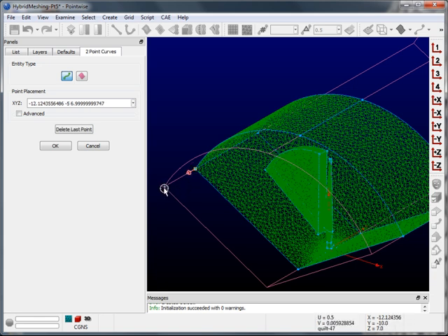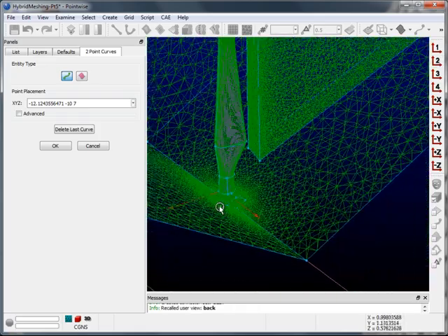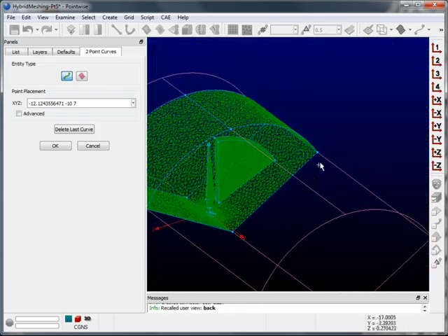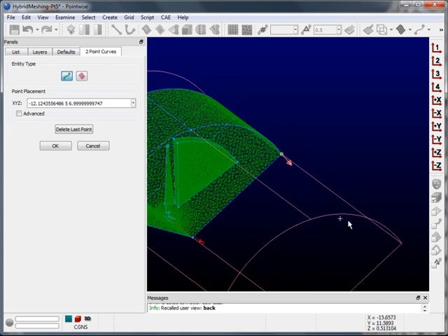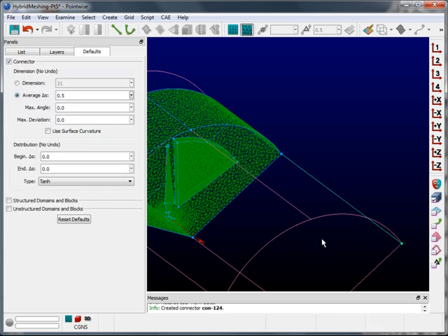So I'm going to create a connector from that point to the inlet. Do the same thing, just flip it around here, zoom out, create a connector that's going to act as a path connector for this path-based extrusion to the outlet. Okay,